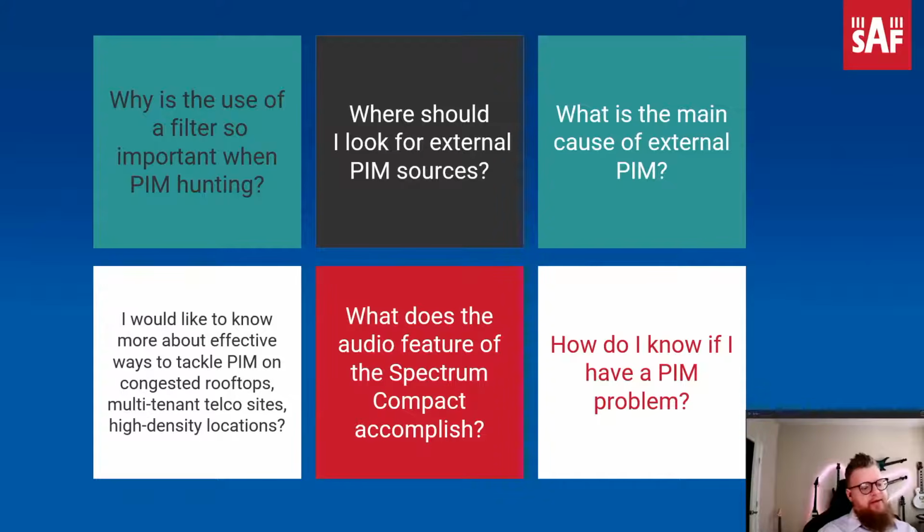So as you get closer, the pitch increases, and this is all dependent on your settings. Keep in mind, you've got the squelch line and then the max line. So within that window, you will have the pitch increase or decrease depending on how far away you are from the PIM source. And you don't even have to look at the screen to verify that. You can hear it in your ear, or like with Heather, you can actually plug it up to a speaker if you wanted to. So it's just a simple way to hit the ground running when you get to a site.